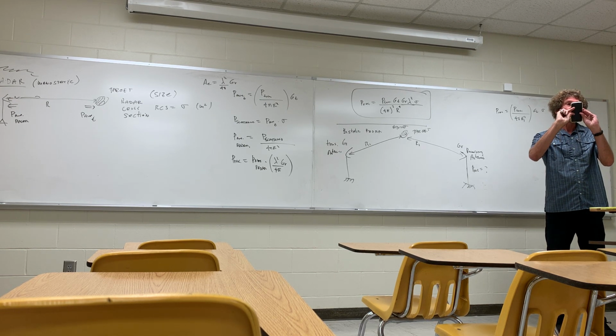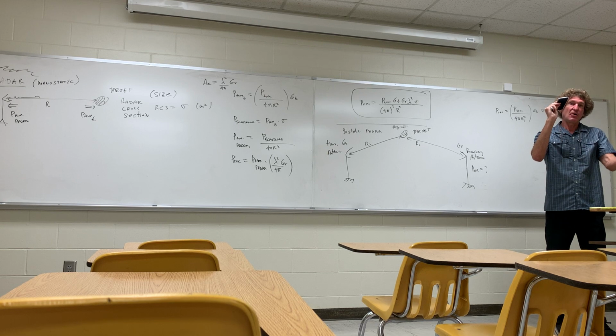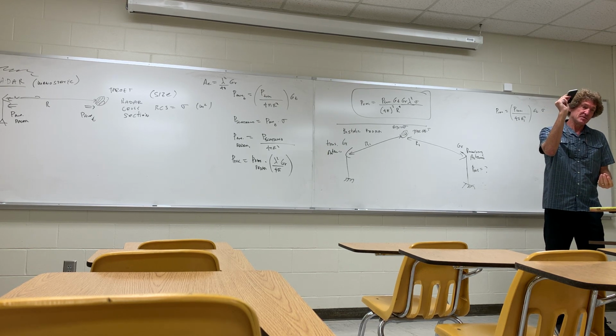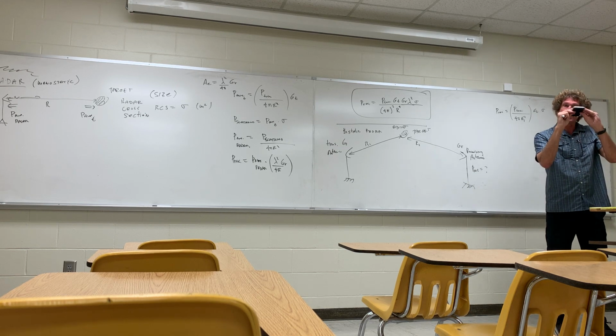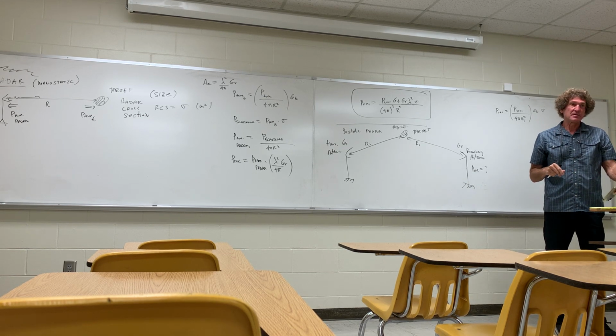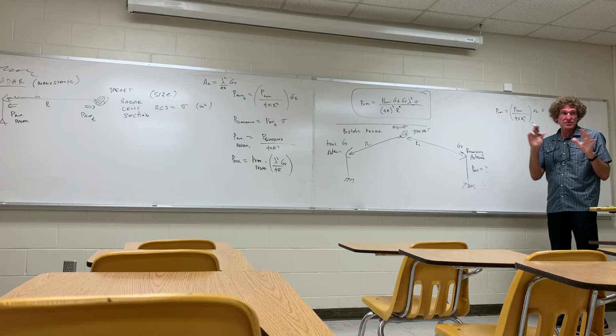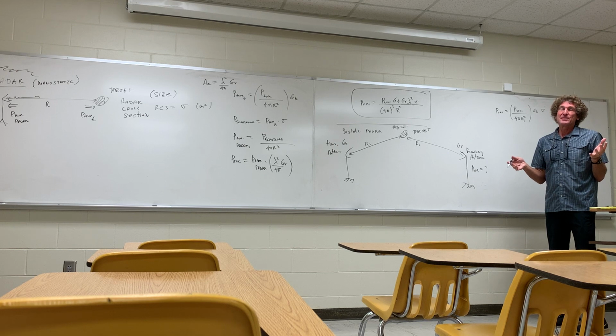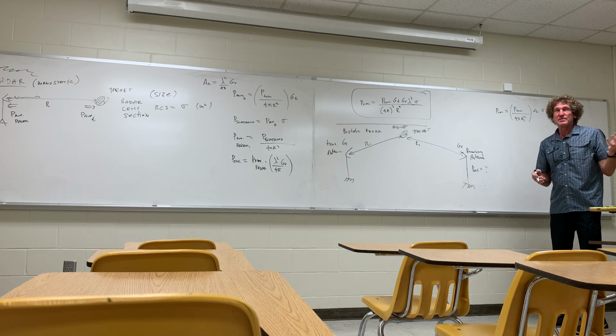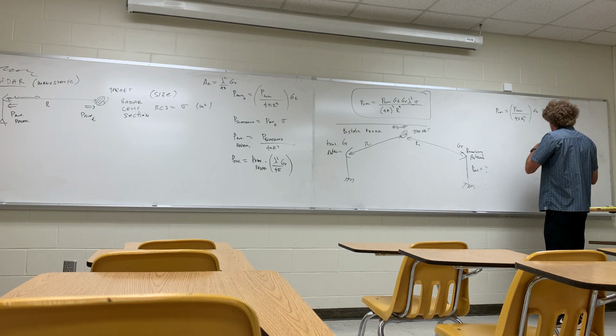That's called the aspect of the target, the radar cross-section being a function of that. But by the same token, this will also look different depending if the radar is here or here, which is really the same thing as the aspect of the target changing. So in other words, this will be a function of angle in general, all right? And it's based on measurements, pretty much, sometimes simulations, but it's well documented.